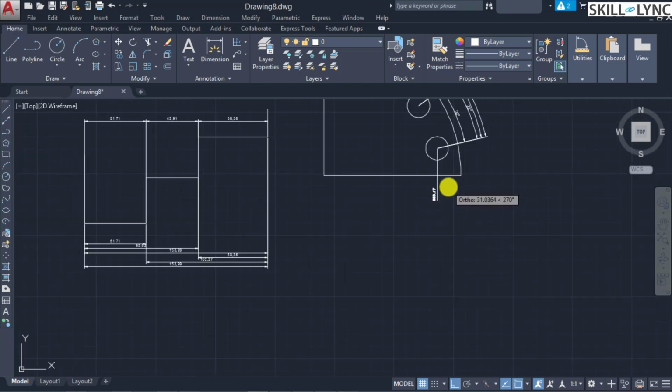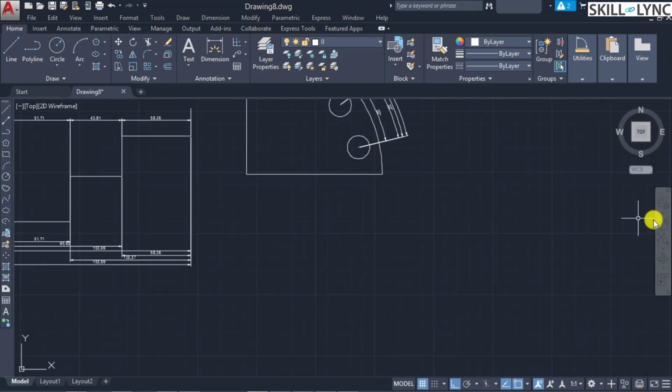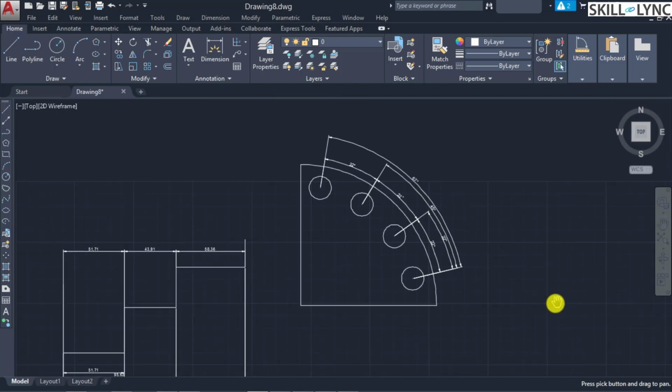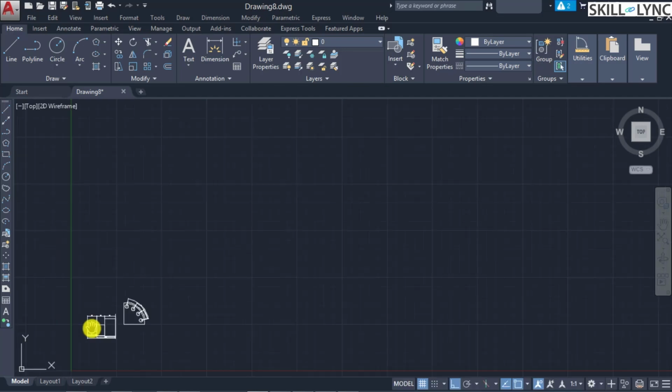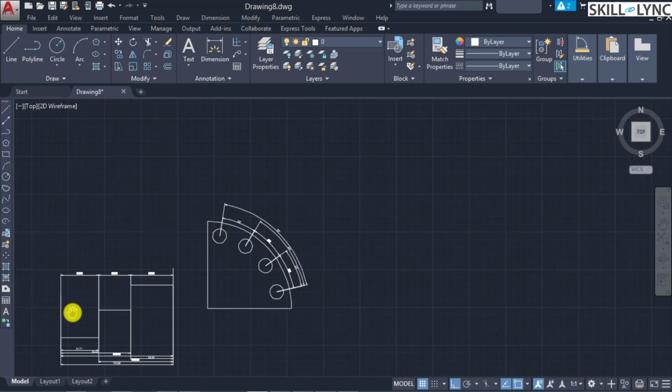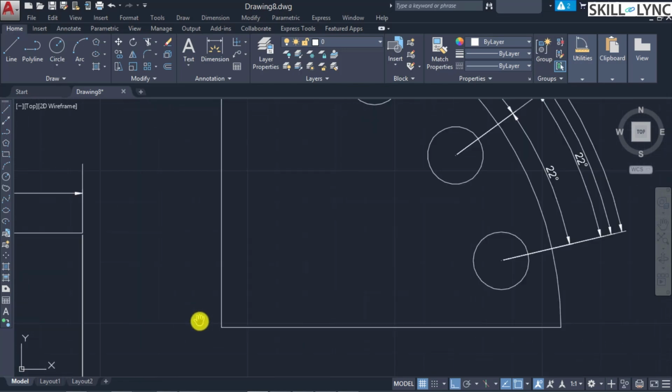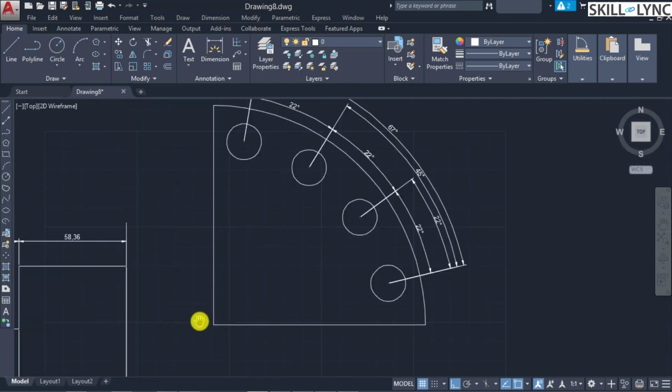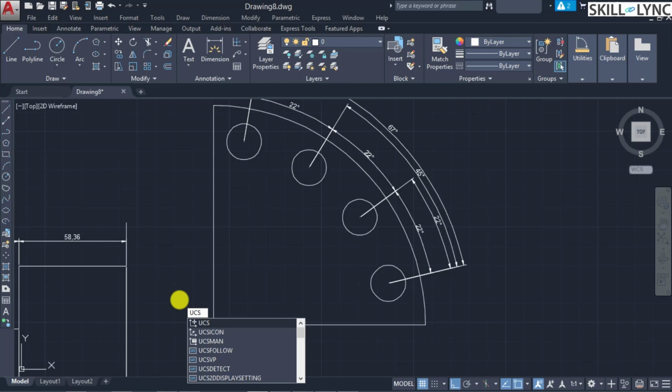If you do not want to do it, and if you want to fix the datum plane, that is, you want the datum surface to lie on these two axes, then you have to move your global reference from here to here. That can be done by modifying the coordinate system reference point, that is, the user coordinate system. In order to do that, you can invoke it with the UCS command, user coordinate system.